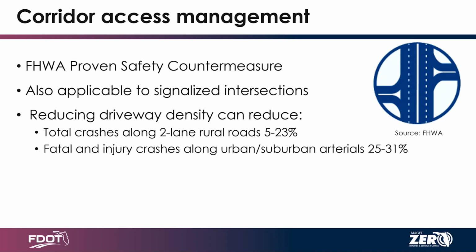Trying to think through some of the other explanation. If you want to really get into that, I think it's either Florida Statute 338 or 335.1, I think it's like .08 to .88 or something like that. But Florida Administrative Code 14-96 and 14-97 have all the access management stuff. 14-96 is, I believe, the rights and permitting, and 14-97 is the access management spacing standards. But they'll also refer you to the appropriate place in the Florida statutes, because that's where they get their authority from.